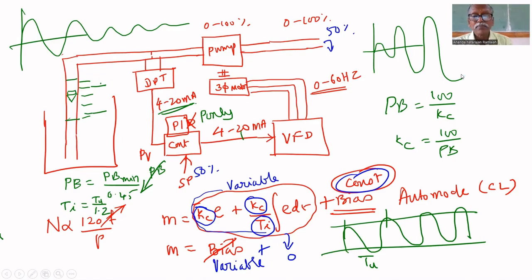This can be found by: it goes up and stays there for some time because it cannot go beyond 100%, you know. That's why it stays there for some time, then comes down. And comes down and stays there for some time and goes up. It means whatever value you gave is greater than Kc max. So it will go up and immediately it should come down. The value for which it exhibits sustained oscillation is called Kc max, or PB min. You got PB min.